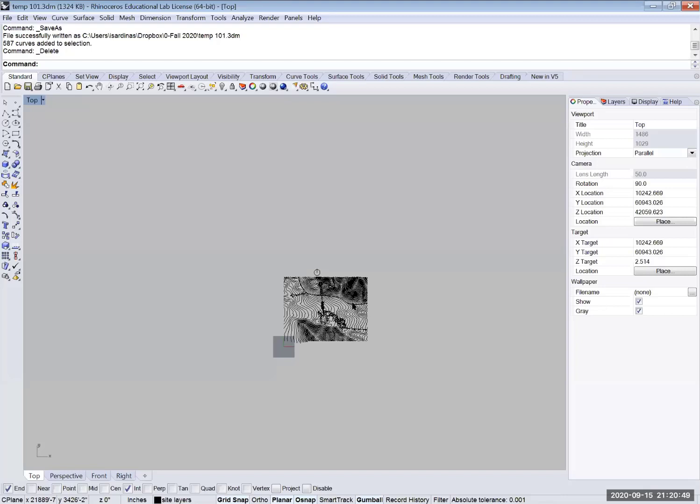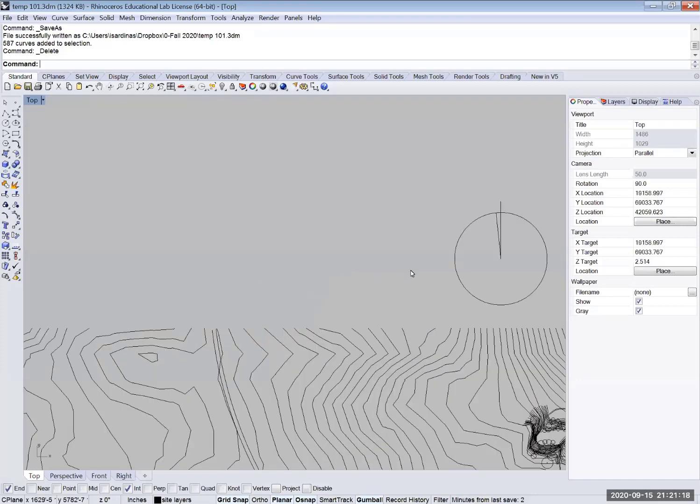So what we want to do is start to think about the project in the context of its site. One of the things I often tell my students when I teach this is to try to keep your building orthogonal, even if that means you have to rotate your site and then later rotate it back. We all know that the site north is off by just a little bit. That was done on purpose.